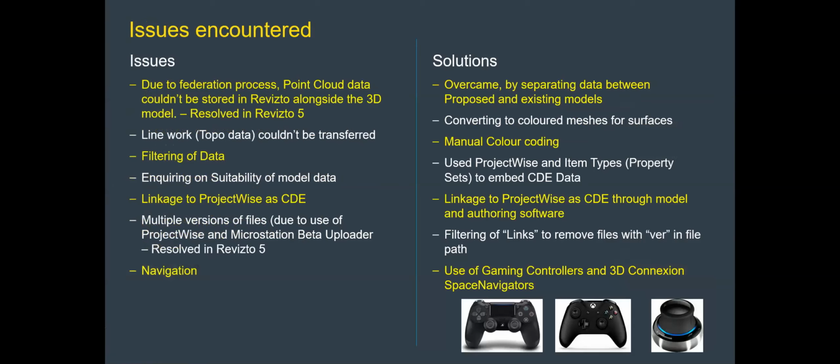And so some of the issues we've had, it's not been plain sailing. There have been some issues. One of them is the point cloud data. Due to the size of the point cloud data and the way we have set out our approach with Revizto, we've had some issues with reprocessing the point cloud data. So we actually separated out the point cloud data from the proposed. This is overcome with Revizto 5, and Peter will talk a bit about that in a bit, where you can pick to load or unload the point cloud data, so people aren't reloading it all the time.